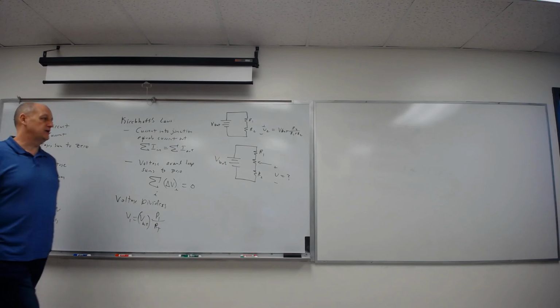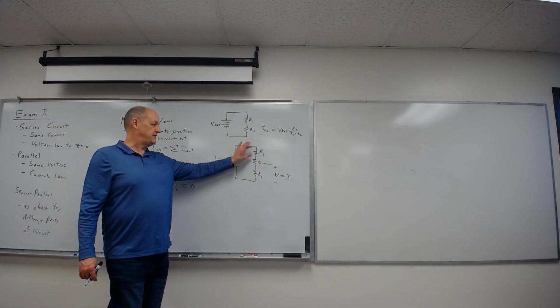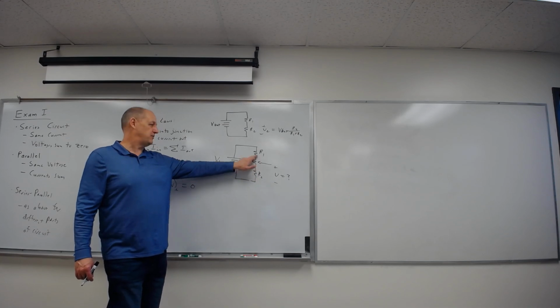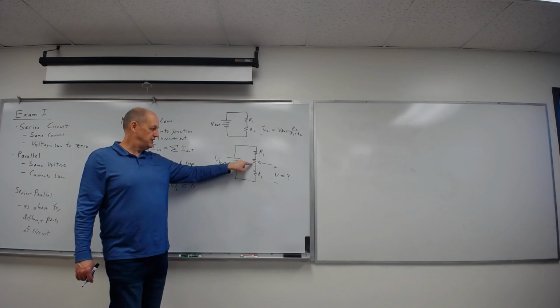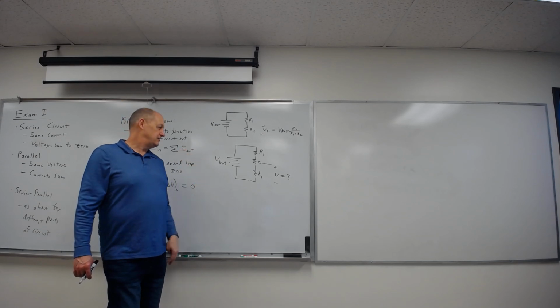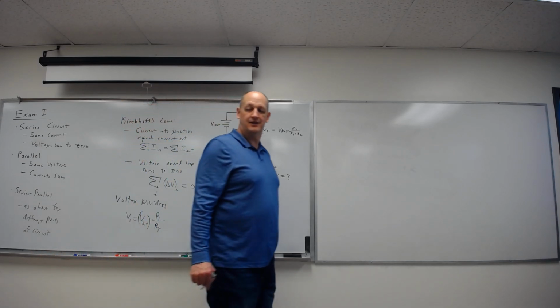So if you do those, just treat this as a resistor, find the current, find these voltages. The potentiometer is all the way down here. The reading will be that voltage. If it's all the way up here, it'll be those 2 voltages added together. If it's some fraction in between, it'll be the fraction of the voltage on that part of the resistor plus this. All fine? Yeah, I think so.